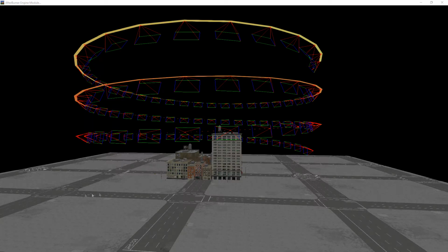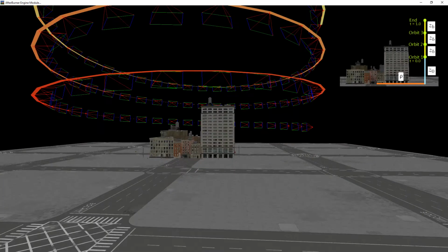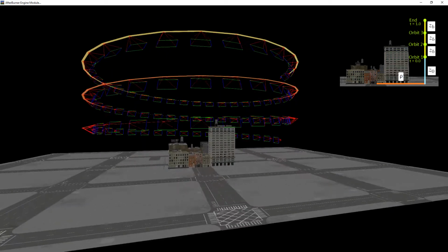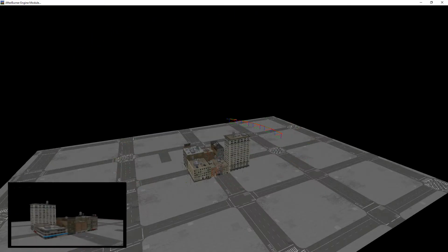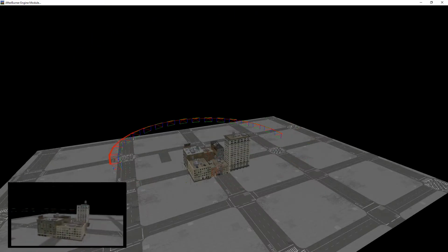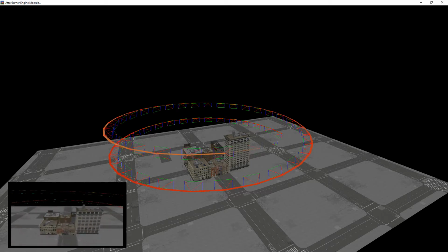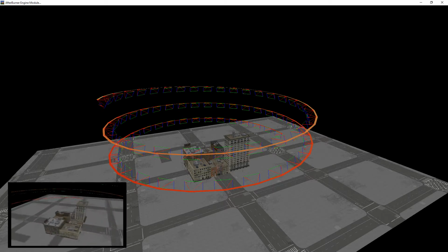First, a flight path is defined. The basic flight path is a spiral with 3 orbits. The parameters are adjustable by experiment and consist of a ground radius ρ, a starting height z0, a distance between orbits zb, and a horizontal focal length f. Once a flight path is defined, the virtual UAV follows a path capturing 90 evenly spaced images. In this case, the UAV looks at the center point of the scene. The real-world analog to this is a set of latitude, longitude, altitude coordinates.